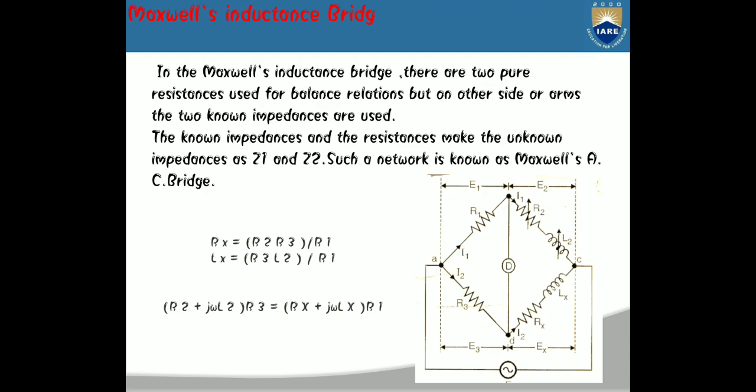The additional complexity of using a Maxwell-Wien bridge over a simpler bridge is warranted in circumstances where either the mutual inductance between the load and the bridge entities or stray electromagnetic interference distorts the measurement results. The capacitive reactance in the bridge will exactly oppose the inductive reactance of the load when the bridge is balanced, allowing the load's resistance and reactance to be reliably determined.